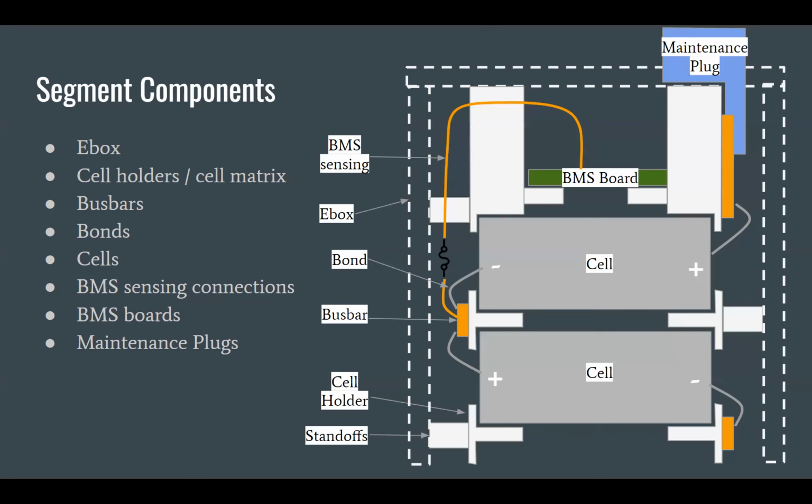You can actually get special types of plugs that have another really small connection that goes through it that lets you detect if you plugged it in properly. The idea is that you can then have safety circuitry that goes through the small connection, and then major power or major voltage that goes through the large connection. And then you can have your circuitry detect that you plugged it in properly before it actually turns on and starts doing stuff. So if you hadn't plugged it in properly, your safety circuitry will be like, well, this plug isn't plugged in correctly. Don't even try to turn anything on. This is not plugged in.